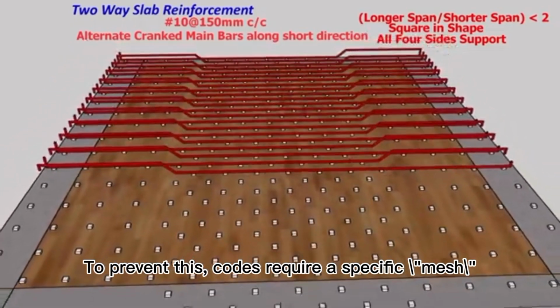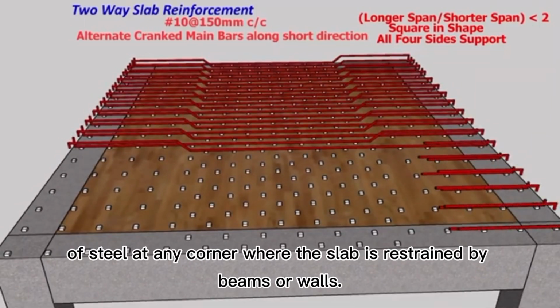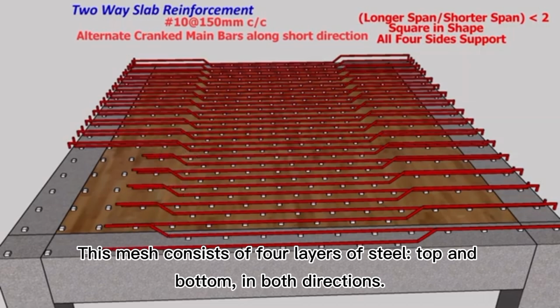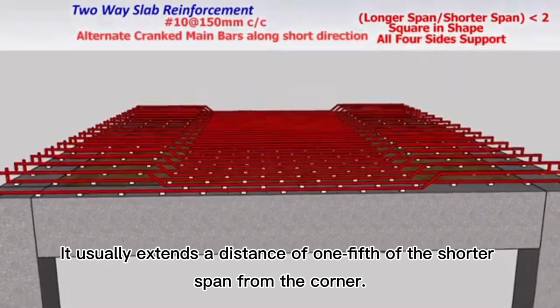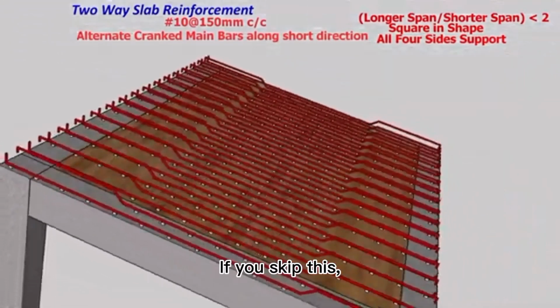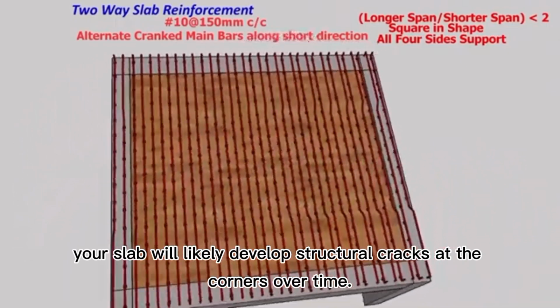To prevent this, codes require a specific mesh of steel at any corner where the slab is restrained by beams or walls. This mesh consists of 4 layers of steel, top and bottom in both directions. It usually extends a distance of 1/5 of the shorter span from the corner. If you skip this, your slab will likely develop structural cracks at the corners over time.